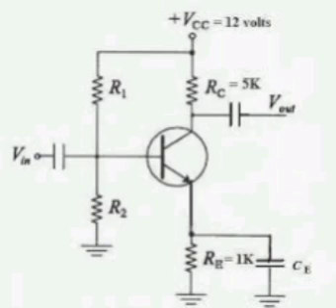Then threshold voltage V threshold equal to V flat band plus root over 4 q Na epsilon Si phi f by Cox. Here the numerator part is root over 4 q Na epsilon Si phi f, and the denominator part is Cox. This is added to VFB, plus 2 phi f. Substituting the values you will get 1.8692 volts.